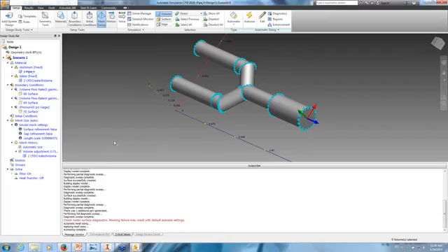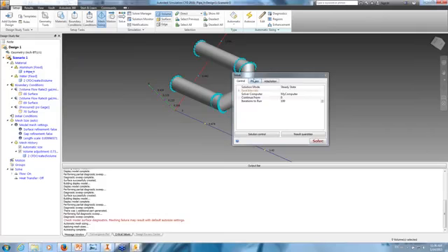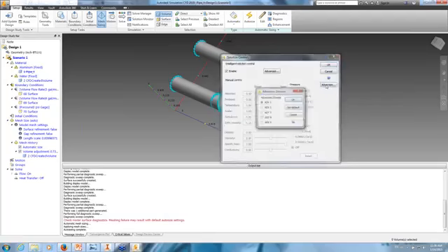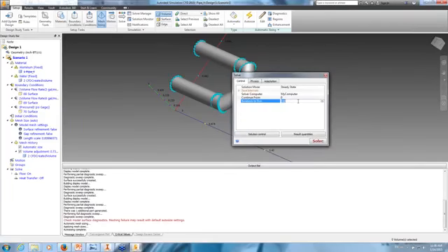Another way of changing the mesh would be perhaps to define a refinement region, a volume box where you would have a finer mesh. I'm going to go to my Solve dialog. I'm going to go to Physics, and in this case I do want heat transfer, so I'm going to click on that. What else? I'm going to change the solution advection to 5 again, and also change my iterations to 500, even though it might not go up to that many. And I'm ready to solve now.